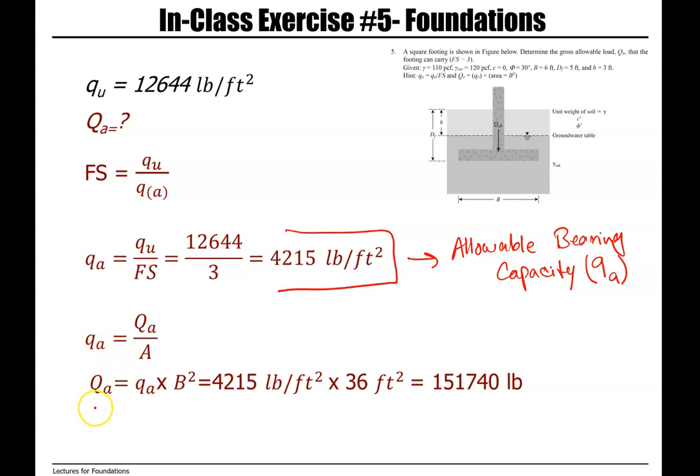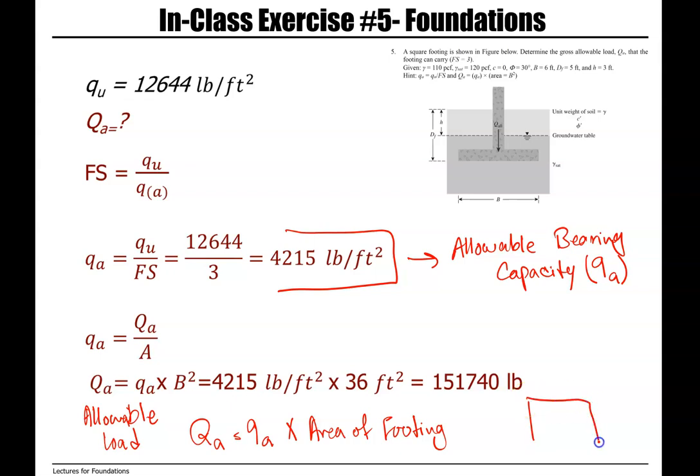And then allowable load QA is capacity times area of footing. We had a square footing, 6 feet by 6 feet.